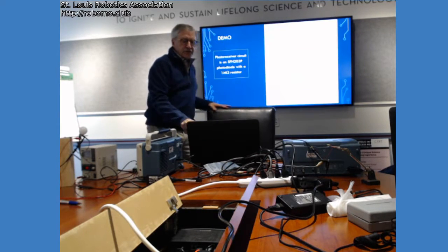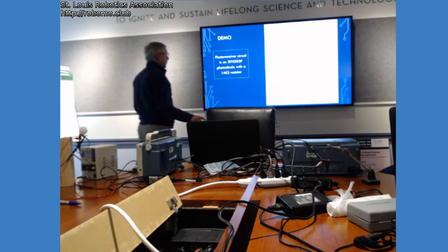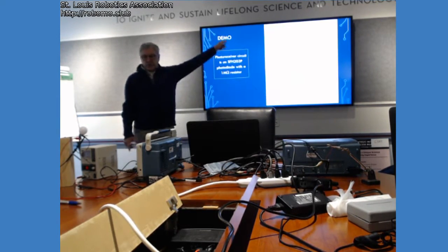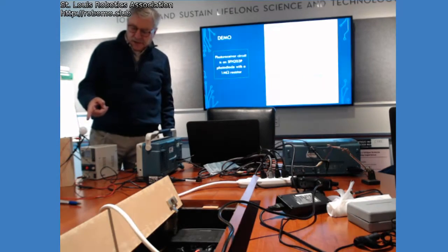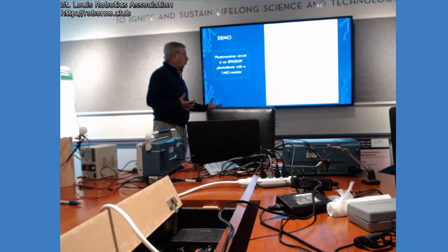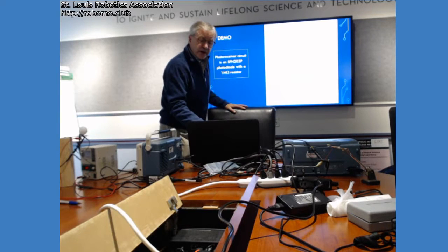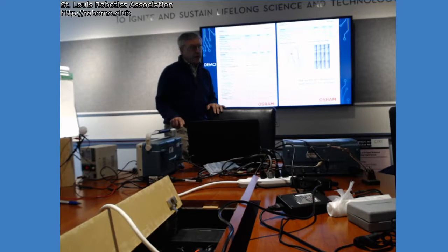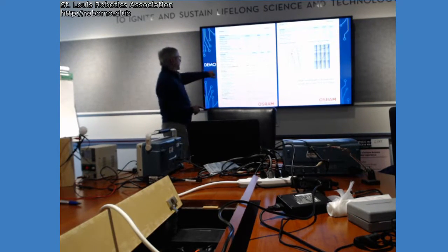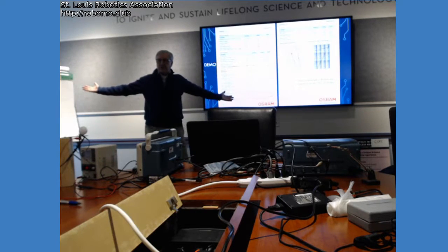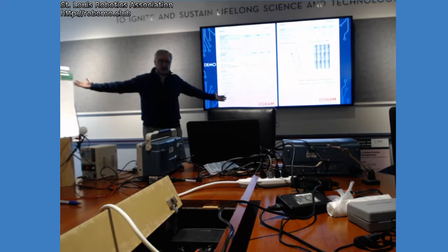So then the last thing, these are going to be eye charts. I'm sorry, but I copied a couple of sheets from the data sheet for this photodiode, just to show you what you want to be looking for when you go through these things. This is an SFH203P from Osram, and this was the main reason for choosing it for the ping pong ball application. It has a very wide field of view, plus or minus 75 degrees, so it can see almost the entire ping pong ball.